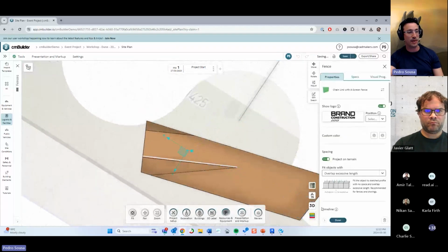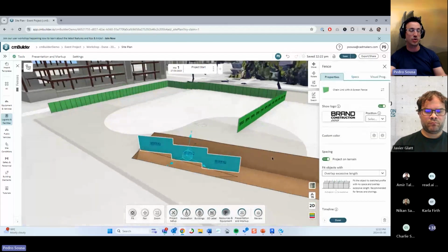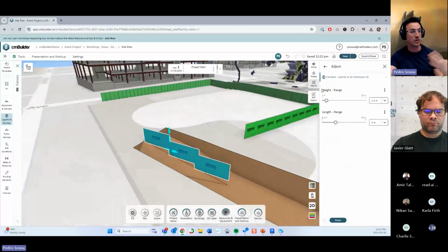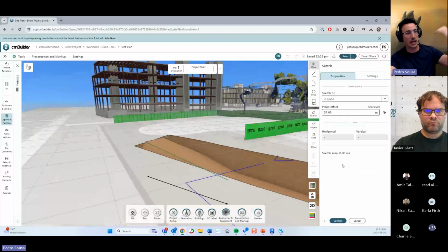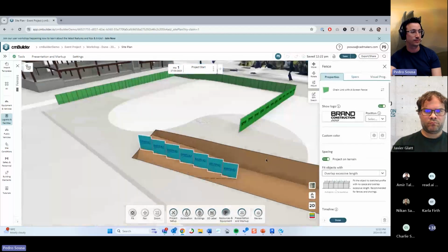But one thing to keep in mind for resources like that, the resources themselves won't align with the sketch normal. They will always be pointed up on Z, on the Z elevation. So you can use this to adjust the shape that you want, with the lengths and so on and so forth, right? But the idea is that your sketch now is aligned with that custom plane. Okay.